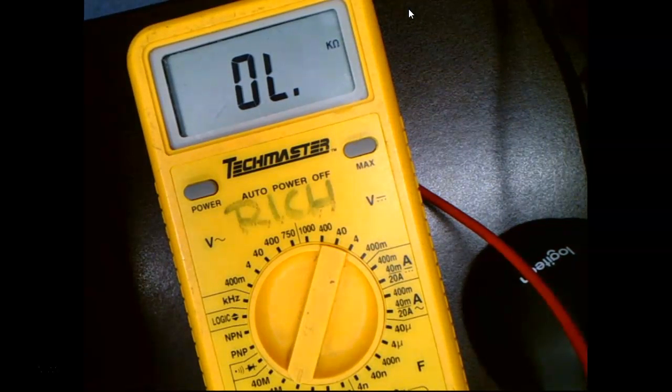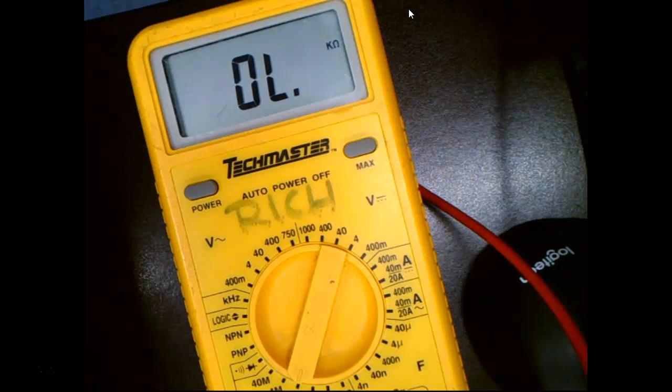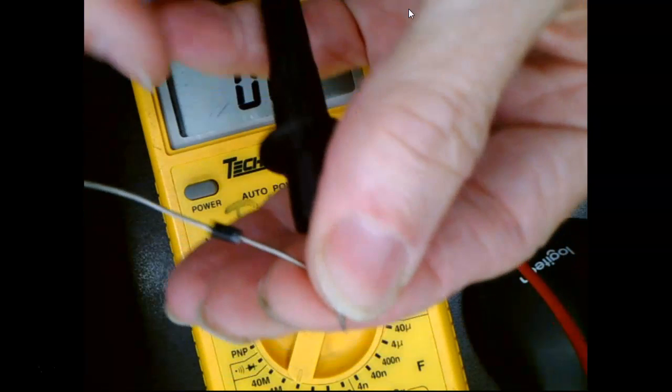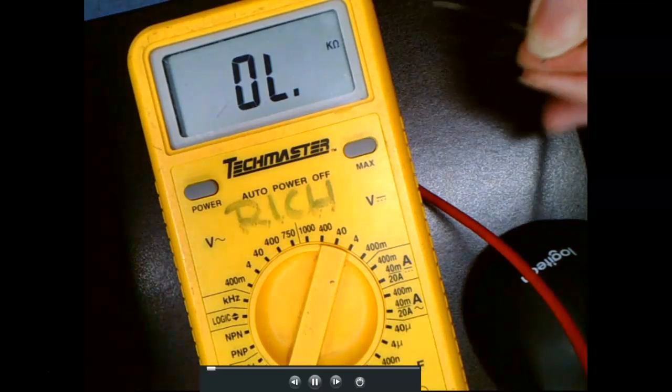And guys, when you put it on ohms and up on these high scales, you need to be leery about touching both of your leads with your fingers, because your meter might actually be doing what I did. It might be measuring you, right? So here, this is the cathode. I can see that one because I can see the line. Here's the anode.